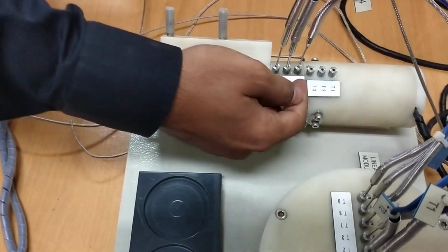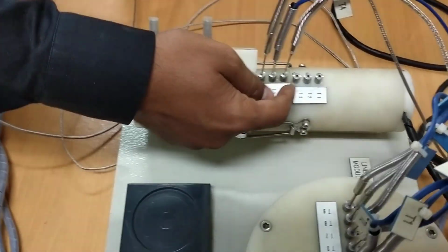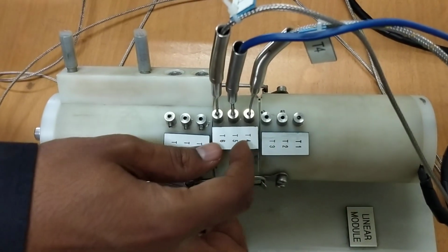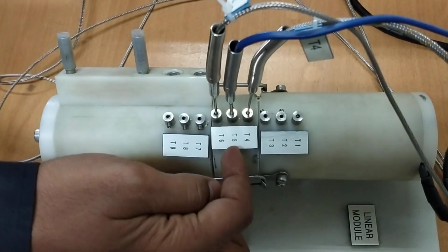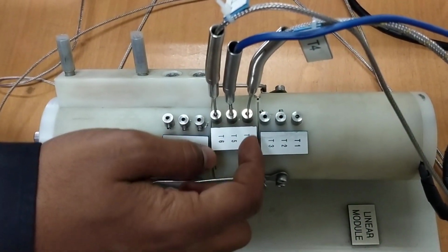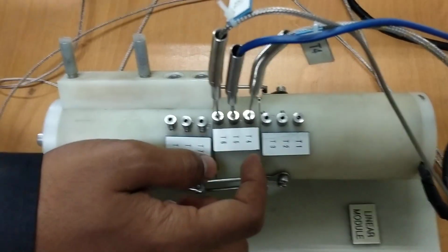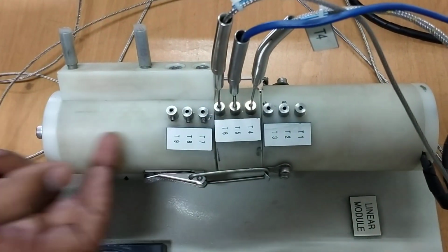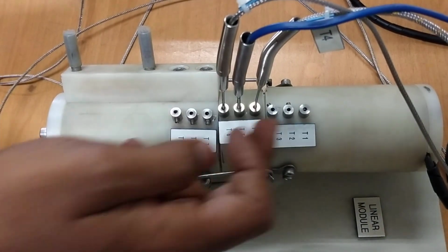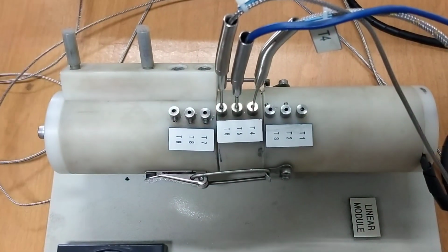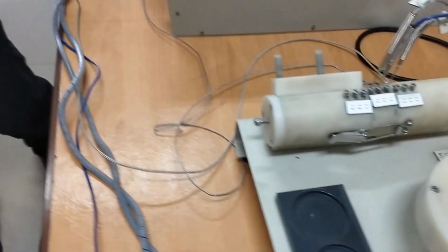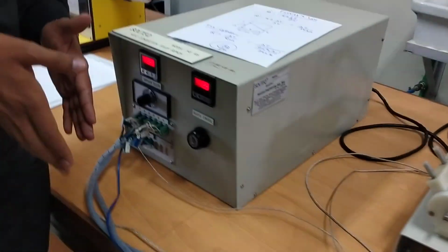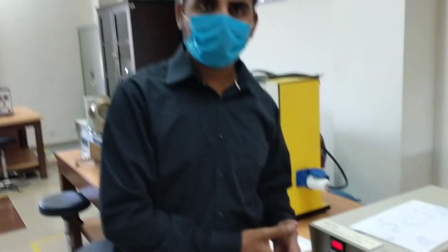So I can use T4 and T6 as the temperature difference, and delta X will be between them. Since these are 2 temperature sensors, one end to the other end is 10 mm, so delta X is equal to 20 mm. The area perpendicular to the heat transfer we can calculate from the diameter, and then Q dot can be calculated from the heater. Same procedure; the readings will be given to you in the class material section.